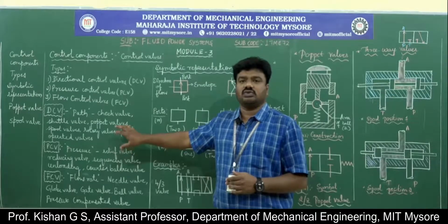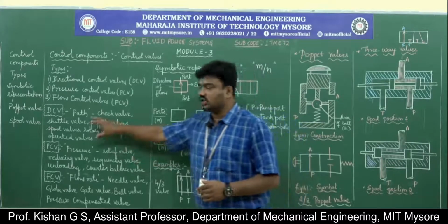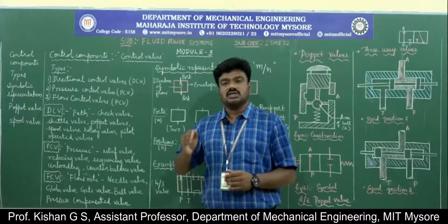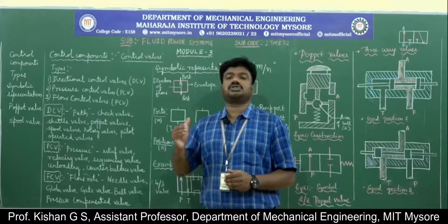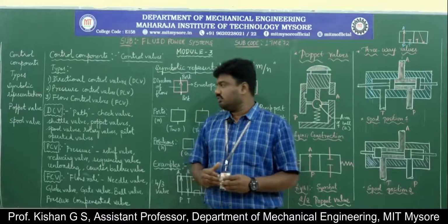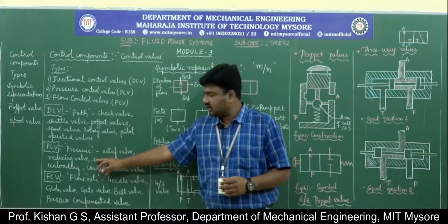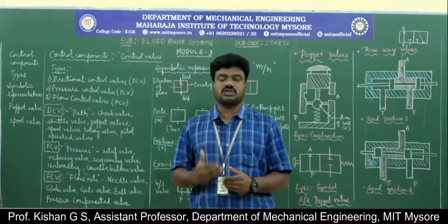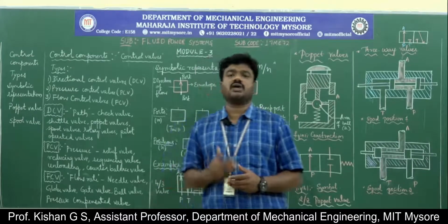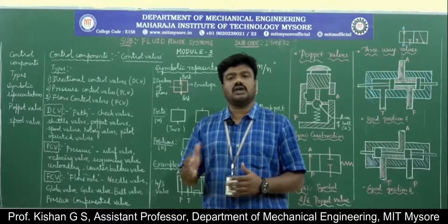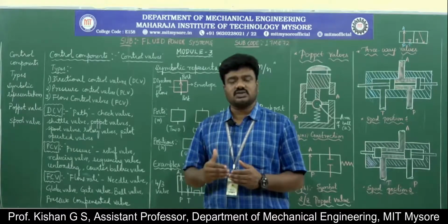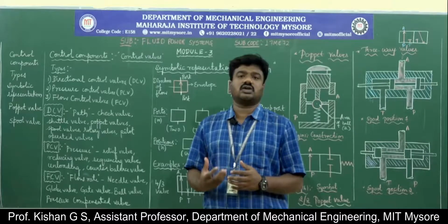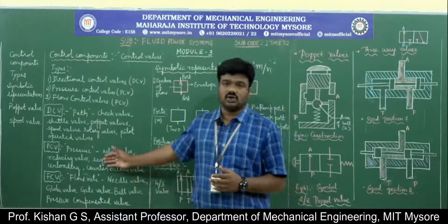What do these particular valves do? These particular valves control the path of the hydraulic fluid from one location to another location such that it leads to the actuation of medium in the defined pattern, followed by the pressure control valve. So these are the control valves that resist the system from being over pressurized, which means to say that it controls the pressure of the hydraulic fluid which is running throughout the entire system. So if the pressure is less or if the pressure is high, how the pressure control valve compensates these things is the concept we are going to understand in pressure control valve.